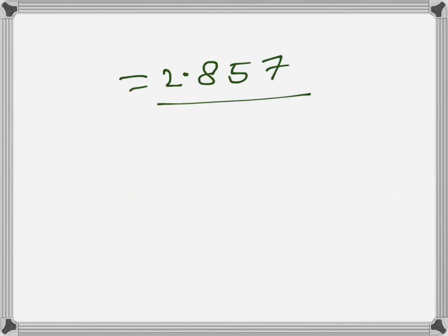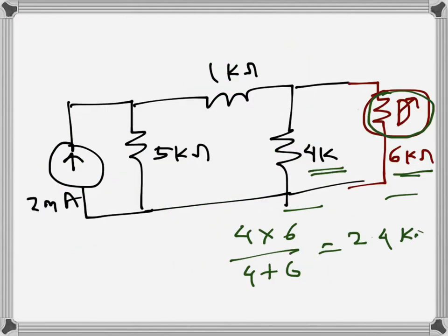So that's the voltage drop, which is much less, and this is happening because the voltmeter resistance is 6, which is very much comparable. If it were higher, the measured voltage would be closer to the actual voltage drop. So I will do another problem which will show that.